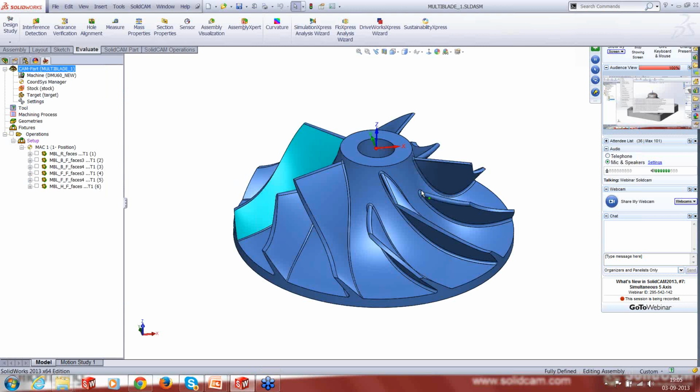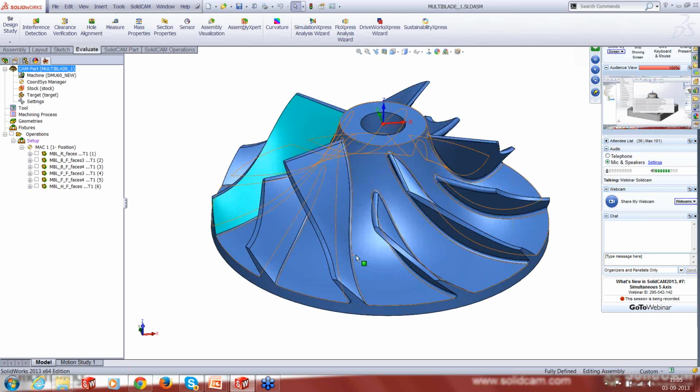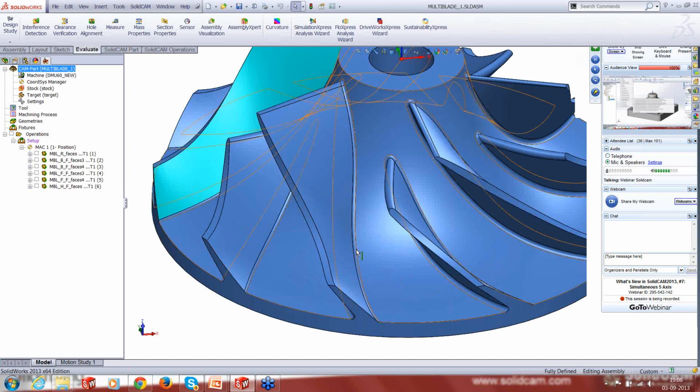There's absolutely no difference. You won't see any difference in your result. You would not get any kind of an error. You can still select, but we generally would recommend not to, because the software is very smart in realizing that you have selected a shroud, and what it basically does is internally it creates a revolved surface of that shroud to create the pattern between the shroud and the hub. And the same goes even for the hub. For the hub, you can look at my pointer, you could have only a 5mm surface protruding out from the edge of the fillet.